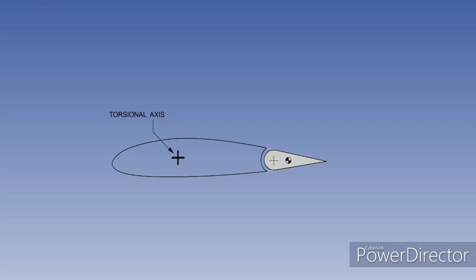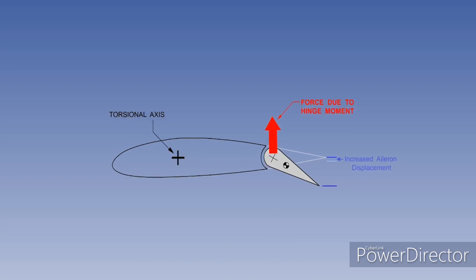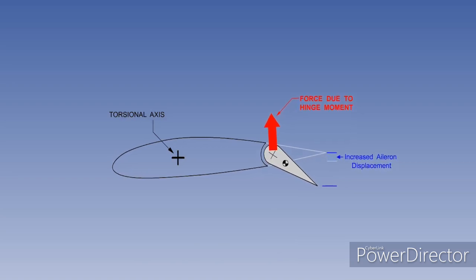Control surface flutter can affect the ailerons, the elevator and the rudder. Of the three, we will consider aileron flutter, being perhaps the easiest to visualize. The movements shown are deliberately exaggerated for clarity. When an aileron is deflected downwards into the airflow, an aerodynamic force will be generated, acting upward at the hinge line. This aerodynamic force will twist the wing about its torsional axis and start to wind up the wing like a spring.